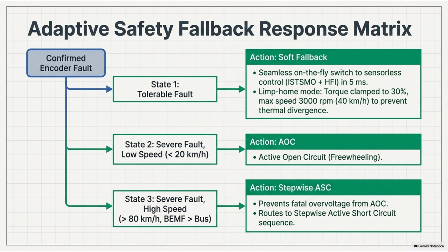Synced clocks. To eliminate the digital hallucination caused by mismatched timing between the RDC chip and the MCU, the hardware design rules now dictate that both components must share a single, high-precision hardware clock source. Oh, so by tying both the decoding chip and the main microcontroller to the exact same crystal oscillator, you eliminate the phase sliding. Exactly. The specification notes this keeps the phase error to less than 0.5 degrees. If the clocks are locked together, the MCU will physically never attempt to read the register at the exact nanosecond the RDC is transitioning the voltage. The setup and hold time violations are just architecturally removed.